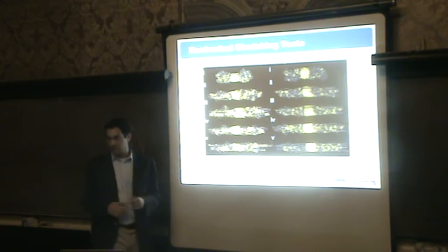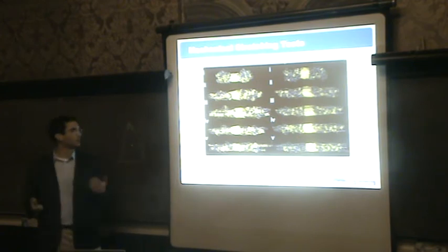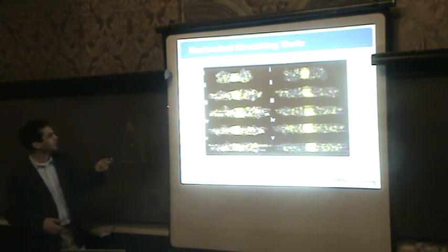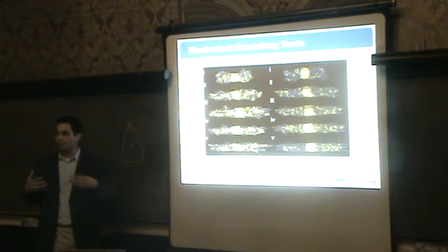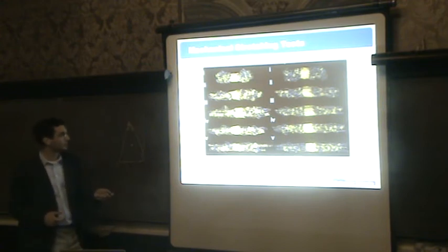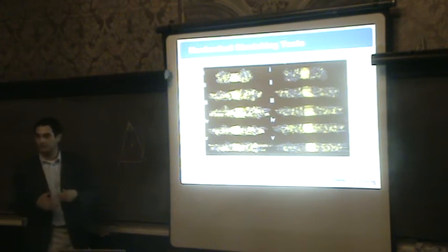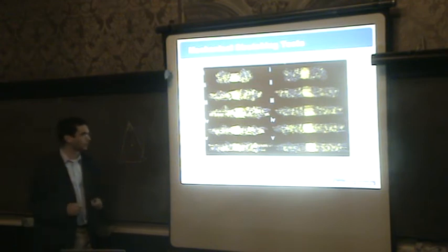The key observation here is when you look at these chains, and basically maybe pull half of the chains this way and half of the chains the other way, what you observe is you again have this sliding kind of motion, which relates to how the hydrogen bonds break the crystal, and basically the material yields through the breaking of the crystals. So initially stretching the amorphous domains and then yielding at the crystalline domains is what we observe.